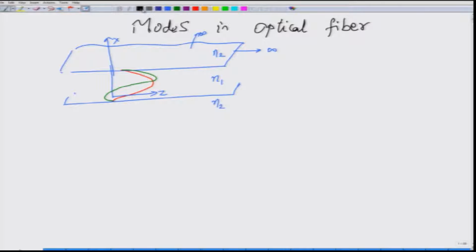So these were the structures that we had seen, and these patterns were associated with TE or TM modes. For a parallel plate waveguide, we actually called them along with a certain additional index. We said that if n denotes the number of half cycles, then that would be my mode nomenclature. I could equally have chosen the number of minima, and that is sometimes done. So if for example n denotes the number of minima, then TE0 would correspond to the fundamental mode wherein there is only a maximum at the center and the field never goes to 0.